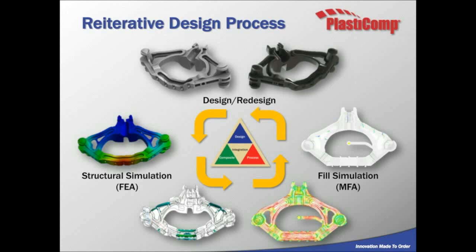And then we can pull up that geometry on our CAD software. We can run FEA, or you can run FEA. We can run mold flows, or you can, and simultaneously, by looking at mold flows and FEAs, we can identify stress loading locations, and we can identify poor fiber orientations or weld line areas. By looking at the two, we can start deciding where we want to gate, where we can manipulate the weld line locations to be, or maybe eliminate them altogether, or where we need to get the fiber orientation we need to withstand the stresses that we're seeing. So it's an iterative process where we're going back and forth between those two simulations. And that's a very powerful strategy.